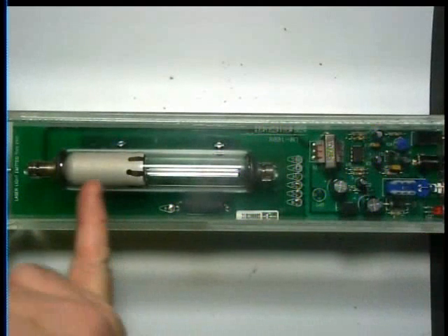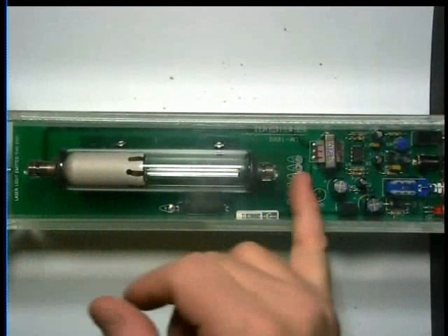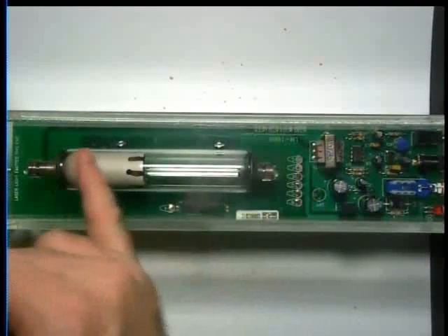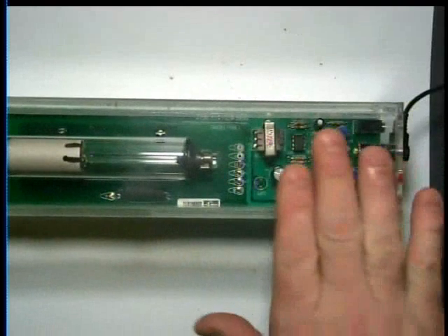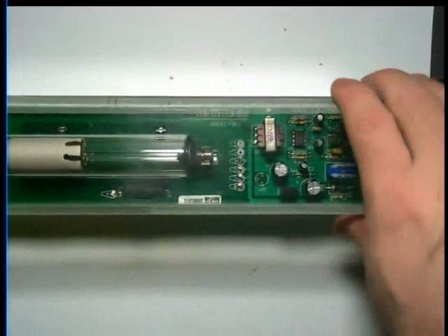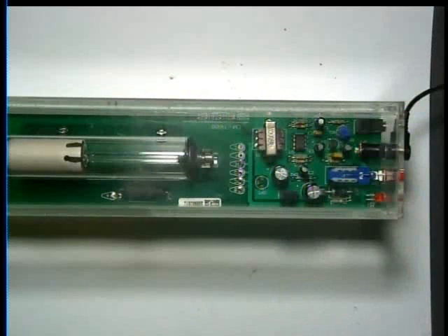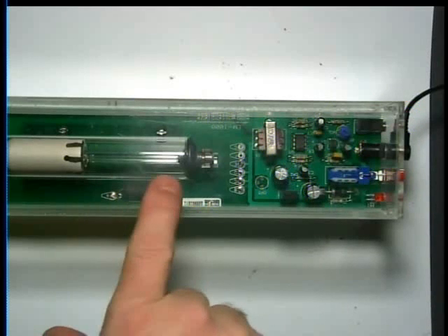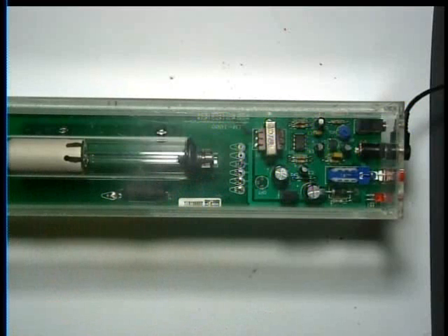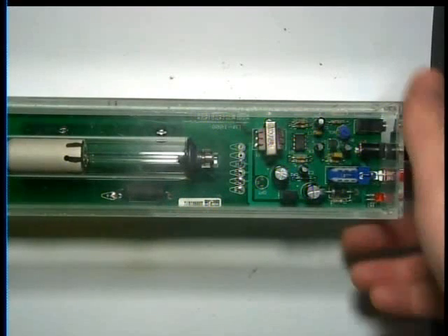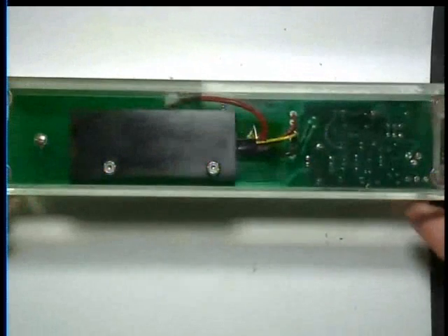So if you look inside here, you've got a metal side over here and over here. That's your optical cavity in here. This stuff back here is to generate your power supply. And the way this one works is it doesn't heat with a match. It smashes electrons into the gas molecules and excites them by electron impact. So there's a gas in here, and between those two leads is high voltage. So the electron flies across and smacks into them with high voltage. And that's how you excite the gas. You get the high voltage, you got a ballast on the other side.